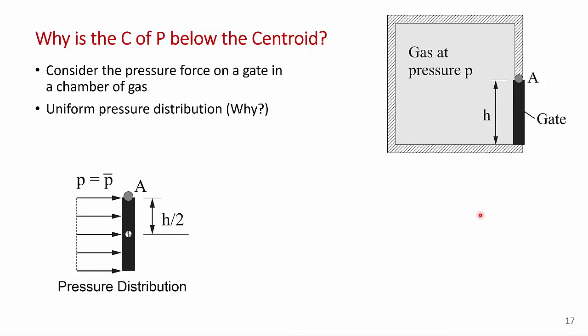Okay, just to finish, I thought I'd talk about a question that often arises. Students often have the concern about why the center of pressure is below the centroid. Why doesn't it act at the centroid? Well, to try to give you a physical feel for this, I'm going to describe two cases. So first, let's consider a container over here that just contains gas. So let's say air, slightly pressurized air. And we're trying to calculate the pressure force on this gate here.